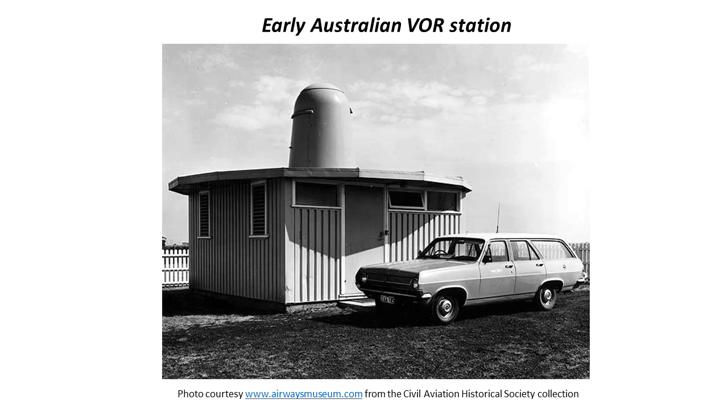Now we'll look at the conventional VOR. You'll see from this fairly early example from Australia that it is much more compact in size compared to the Doppler VOR and is correspondingly considerably cheaper. The antenna system is mounted on top of the equipment shelter. The roof of the shelter forms a small earth counterpoise for the antenna.